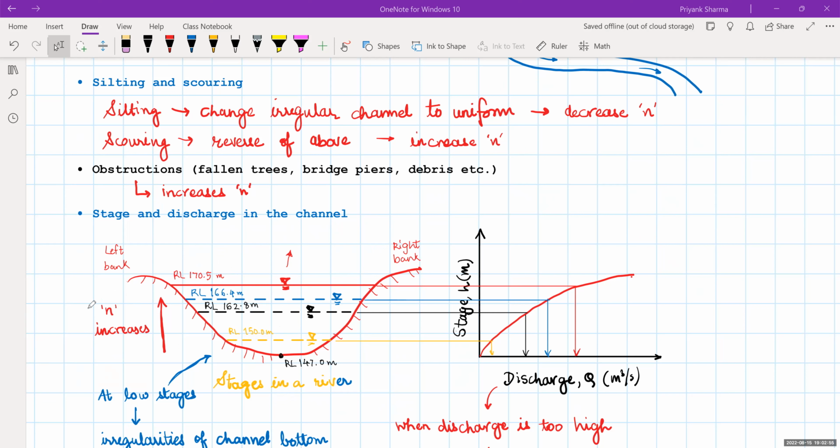Now this particular curve is called the stage discharge curve. While we were discussing the measurement of velocity using a current meter, we discussed this. When the velocities are measured and the cross section area is already surveyed, for different depths of flow, what would be the discharge? That is the volume, and that is analyzed and the discharge is arrived at. So with the stage discharge curve, if you have the information on stage, you can easily quantify what is the discharge at that given stage.